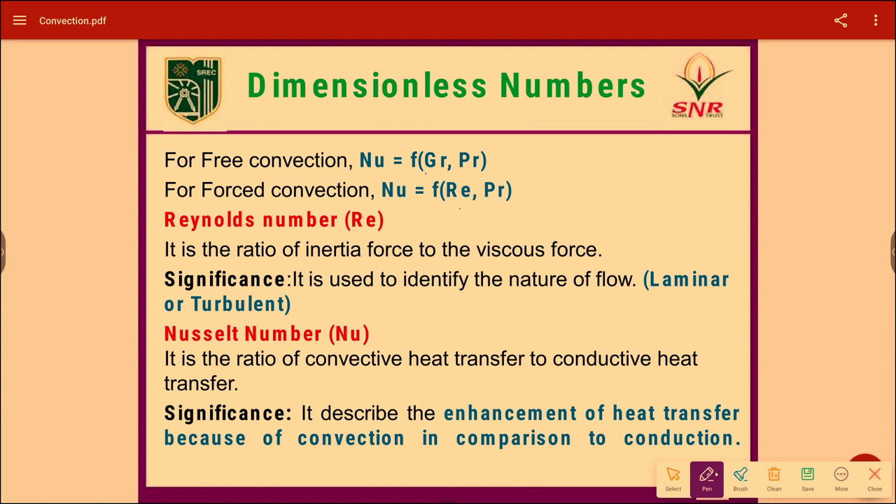All these things we will see one by one. First, let us see what is my Reynolds number. So we all know that the convection mode of heat transfer depends upon the mixing of the fluid. Higher the mixing, higher the heat transfer. Now we have to keep in mind the flow. There are two cases of flow. The flow may be either laminar or turbulent. In laminar flow, the flow will happen as lamina of sheets, where the mixing will be less.